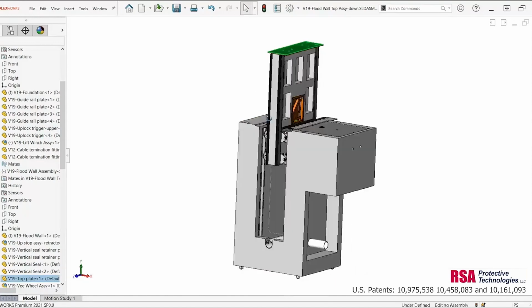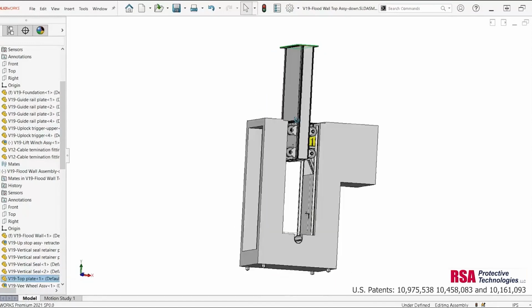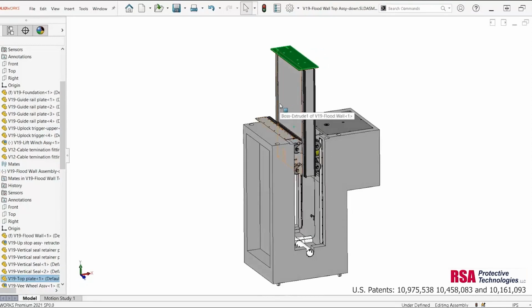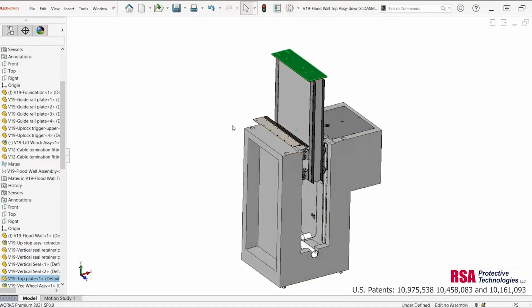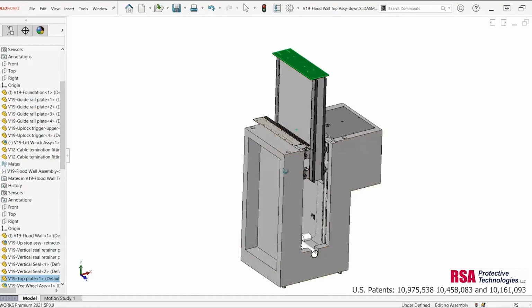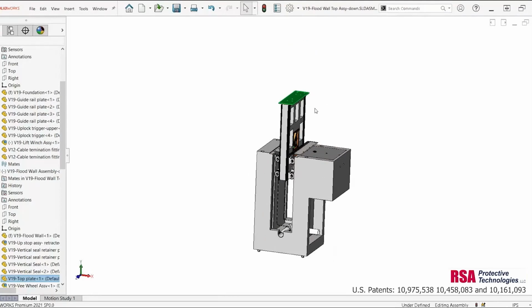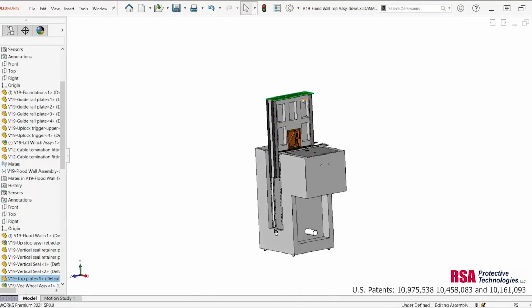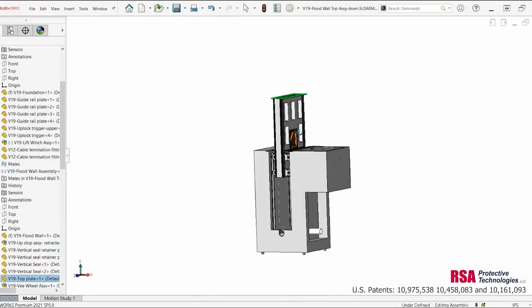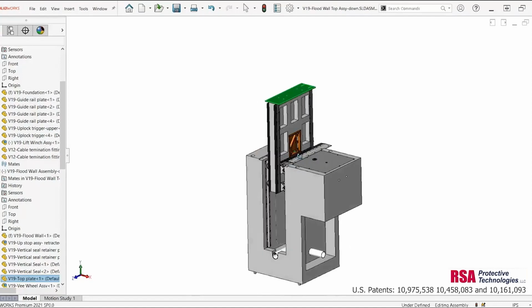How much flood are we trying to protect against on this side? If this is a coastal location and we have wave action, we have hydrodynamic loading against this wall. If it's against a river, we may have water current. And in some areas of the United States, particularly the southeast, we have wind loads when this is in the extended position, especially in places that are prone to hurricanes.